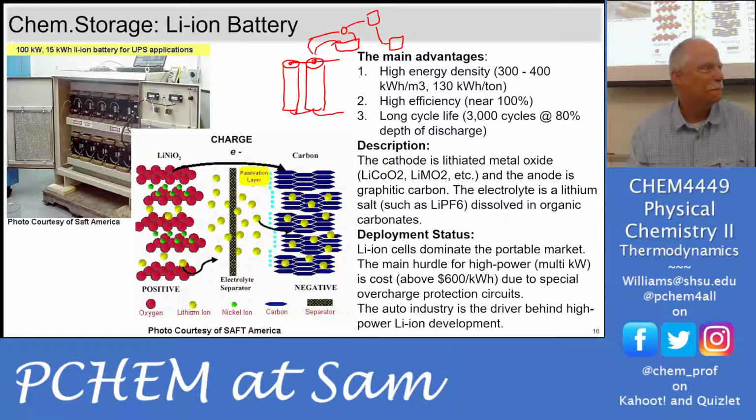So, you can't just solder it? No, because the heat is too slow. The nickel strips conduct the heat away so fast, and then the whole thing has to heat up, so it damages the battery. It's a damage problem. If you spot weld it, you can do it very quickly, with an intense amount of heat but in a small spot. That's what he was reading about. He thought about soldering it, but online they were saying no, you really have to spot weld these things.